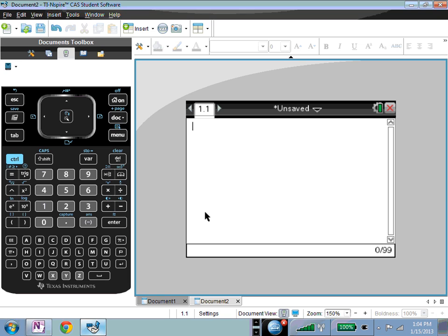We can say symbolically, let me put in a matrix. I just want a square bracket. What was the first entry? That was 1 plus 1 over S, my 1,1 entry, so I'll follow that with a comma. My next one was minus 1 over S, and that now needs to be a semicolon.